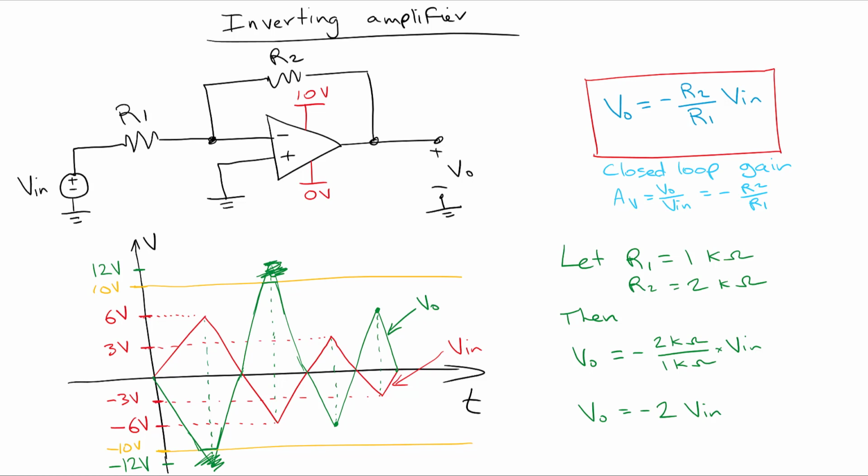And then what would happen? Well, our green line would never go negative. So let's draw what it would be, and I'll use a super thick line. We'd never go negative. We go positive like so across, never go negative, and then go up like that. So that's if we had 0 volts as the negative voltage rail.